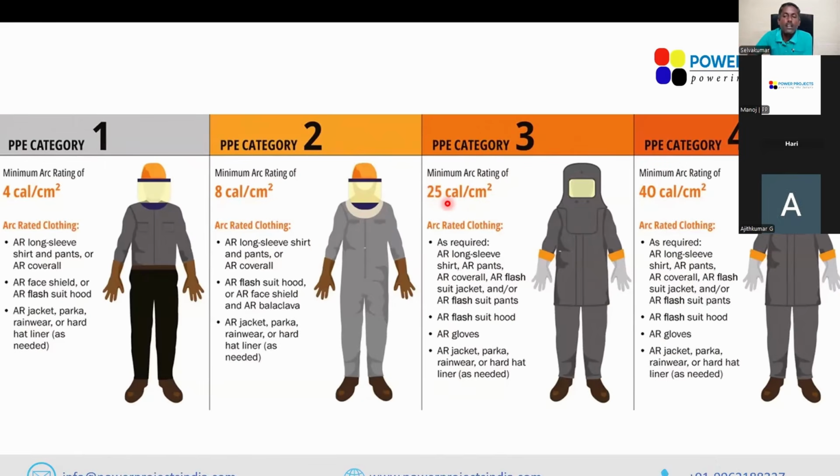One, limiting the short circuit current itself. Second one, limiting the duration, which is pretty much easy. There are multiple methods, like a maintenance switch, or instantaneous settings. When you're going for live maintenance, group settings, there are multiple things to achieve it.